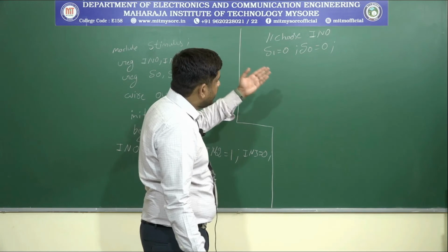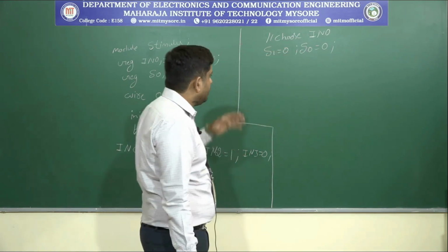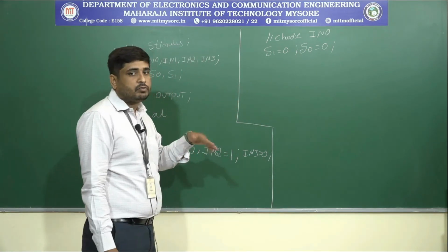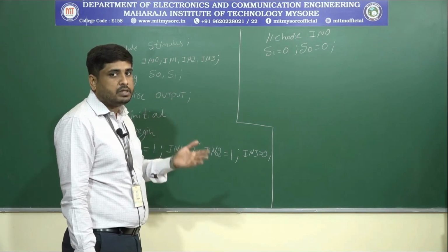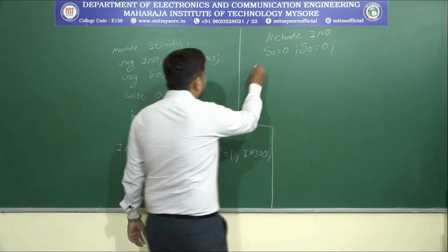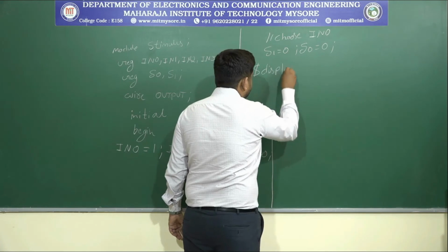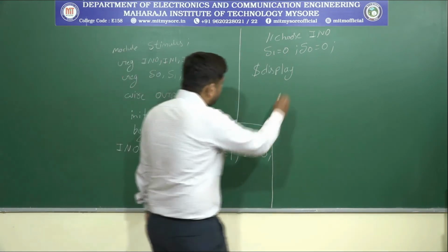After you select IN0, that is S1 is equal to 0 and S0 is equal to 0, you have to display the data. How to display the data? We already discussed in the previous module. That is, we use $display for displaying the result. So here, $display.